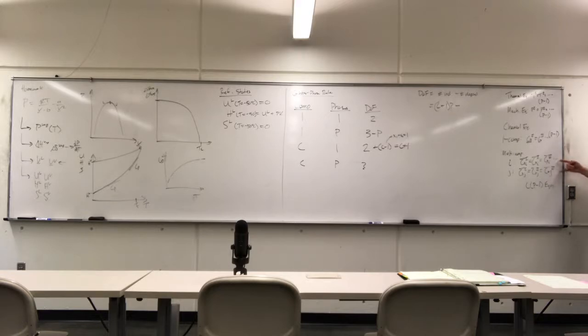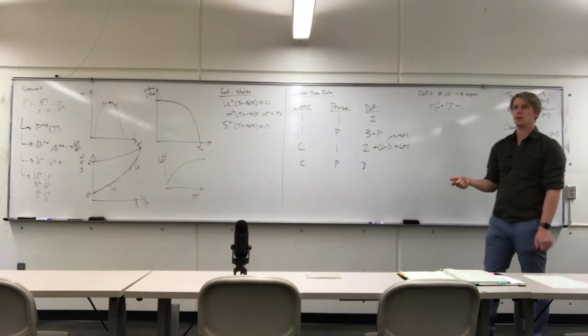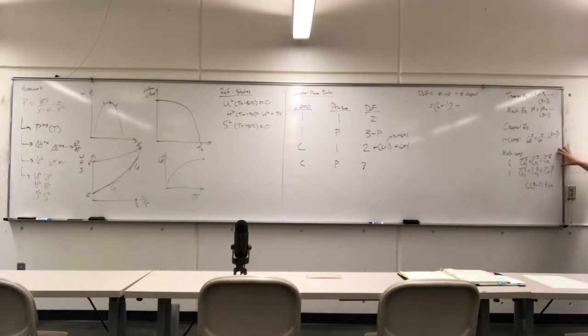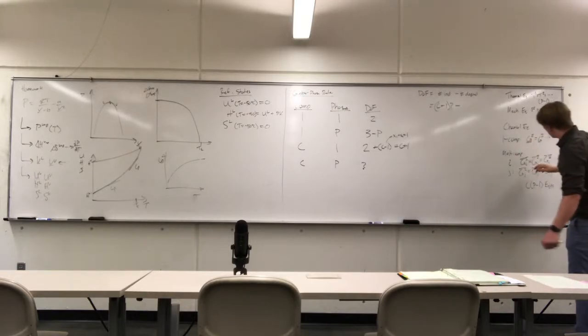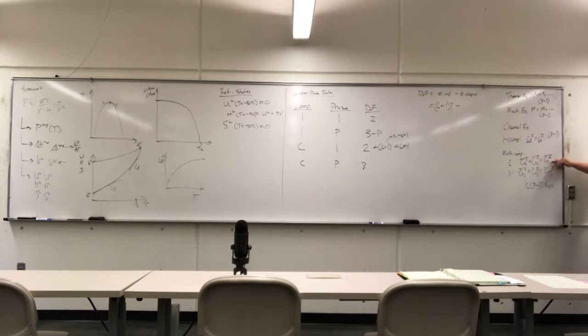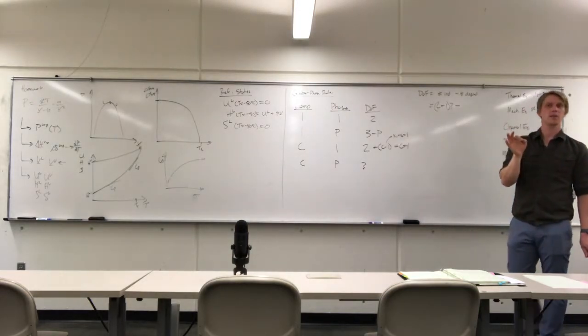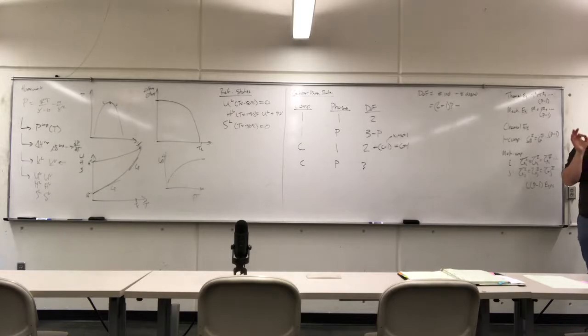And all of these properties change as a function of temperature and pressure. So as the oil flows through a pipeline, let's say a subsea pipeline, which is really common in offshore production in the Gulf of Mexico, your temperature is going to be dropping as you flow down the system. Meaning, all of these are going to change as these change. And so it just becomes a very complex numerical mess. And that's why in our definitions of the partial Gibbs, or our definitions of the enthalpy, or even the definitions of the Gibbs, the mathematics become very complex, and so what we try and do is define the functions in a way that makes them the most useful and applicable. This becomes a very complex problem very quickly.